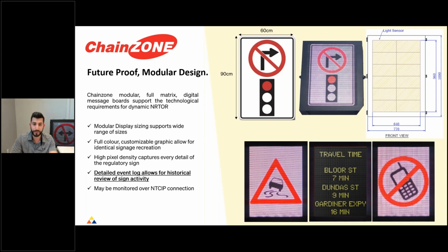Of course, if you just have this sign active with no static supporting signage, there will also be calls on redundancy. So what if the sign fails? I'm not going to tell you it's not a possibility. It is a small possibility that a sign could fail. And in those situations, perhaps it's good to have a second sign for redundancy, to include two signs, one on each side of the intersection.